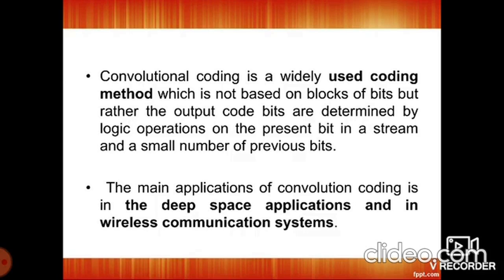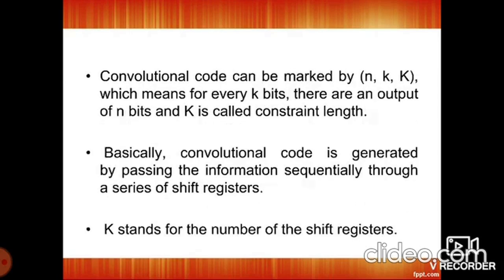The input bits are stored in a fixed length shift register and they are combined with the help of modulo 2 adders. The main application of convolutional coding is deep space applications in wireless communication systems. The operation is equivalent to convolution and hence it is called convolutional coding.